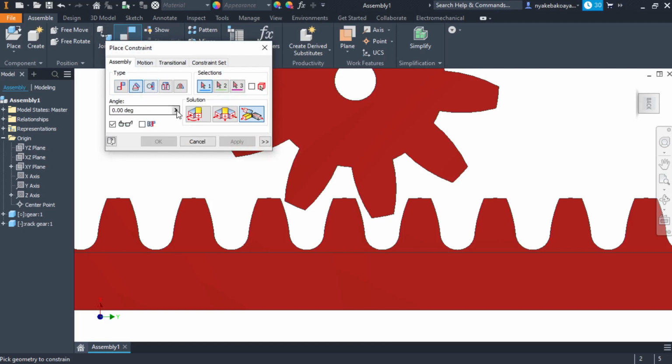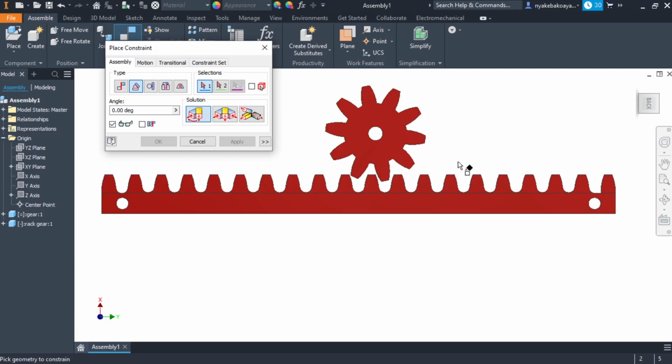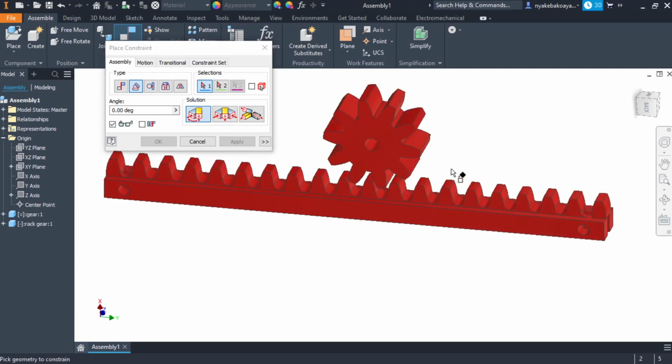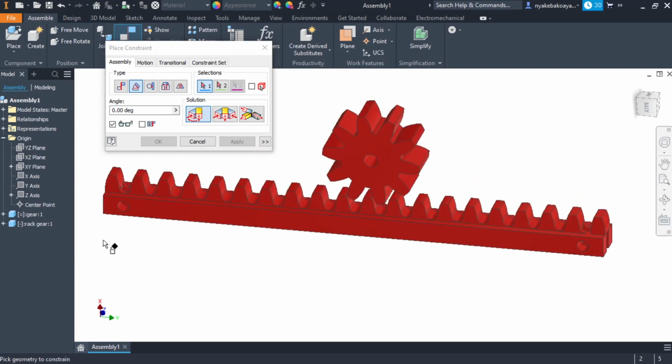Generally we have again three types. We have the direct angle here, we have the unit and directional angle, and this. So I'm going to use this one, but I'm going to encourage you to explore these others because I want to keep this tutorial as short as possible. Once you select the direct there, you will need to select a face. Okay, so I'm going to use this face of the XZ plane there.